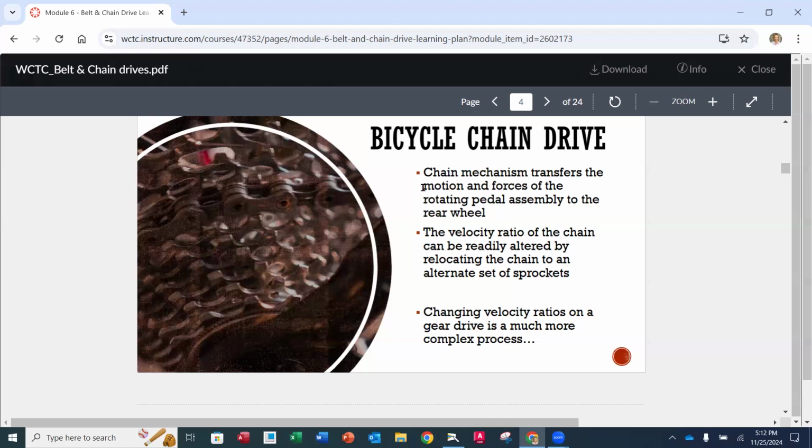Typically, what we do is we start out with a set of assumptions, and then we take a stab at what we believe is going to be the best first steps, okay? Many times in the design process, and this is something that is important to understand, just because we chose a belt size at the beginning, or we chose the size of a chain drive that we started with, we might have to go back and redesign it once we get to the end and we realize, oh, our stresses are too high.